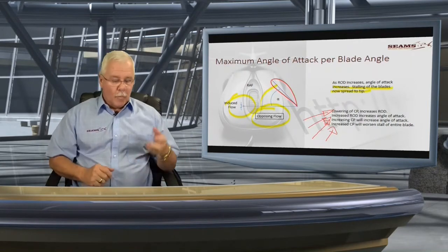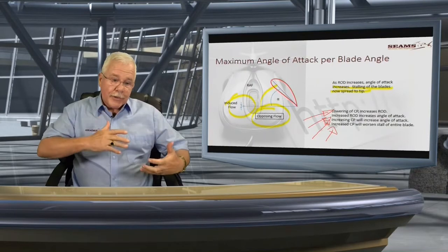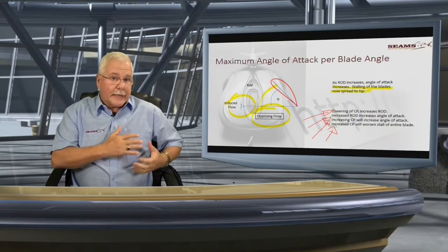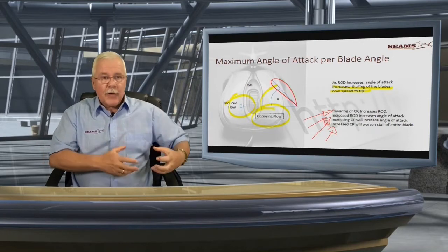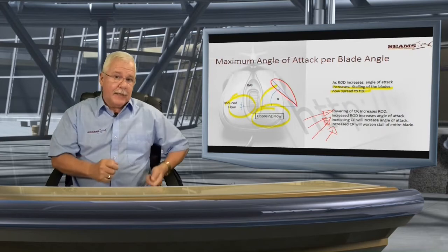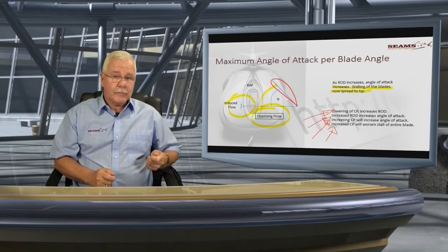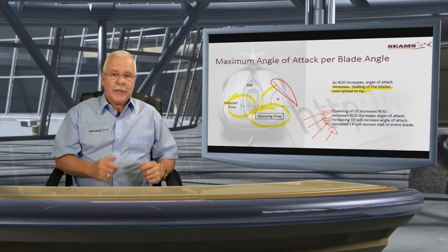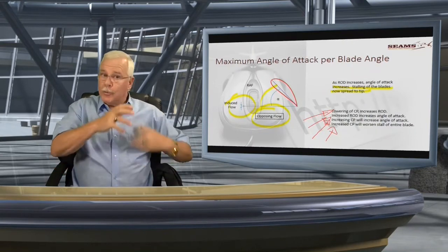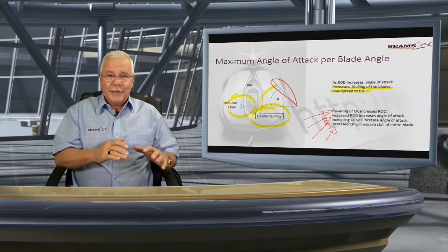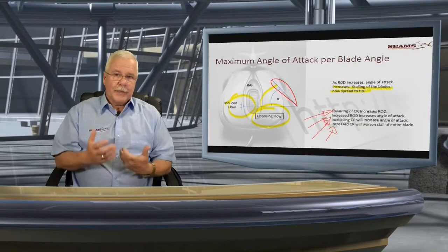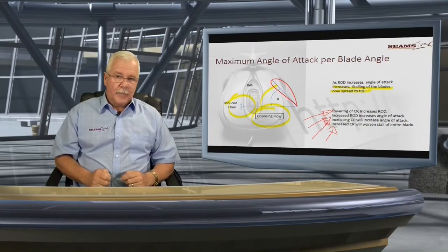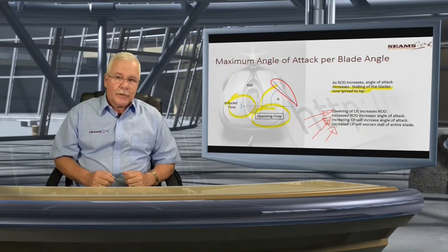Either of the two. Where you are, when you have reached the condition, the collective is sitting at that moment. Remember, all the effects have now come into play for that specific setting on the collective. So if you pull, you're worsening the case. If you dump, you're worsening the case. Obviously for the new setting, it will settle again, and then from there you will have the same. So once this stalling effect is set up and the opposing flows have come to a point, it's not going to work for you anymore.